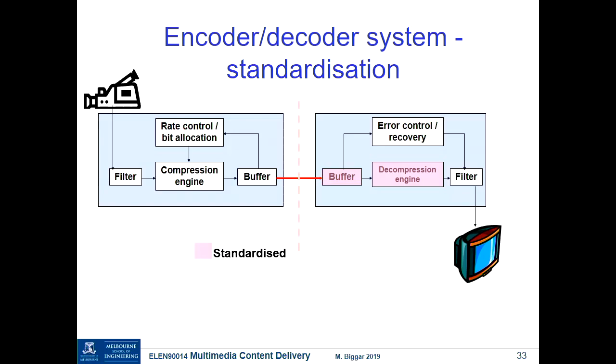And at this end, in fact we'll talk about this later, maybe we want to filter that signal that comes from the camera to smooth it out a bit, to remove the noise. Because if you can imagine what noise is going to look like in a video signal, our DCT assumes that our image is smoothly changing. So the presence of noise means, what does it mean in terms of frequency components? What do you think? Going to be low frequency components or high frequency components?